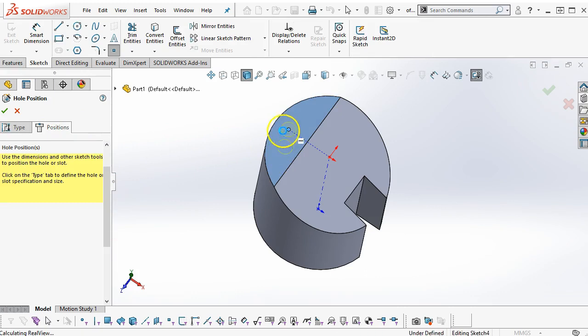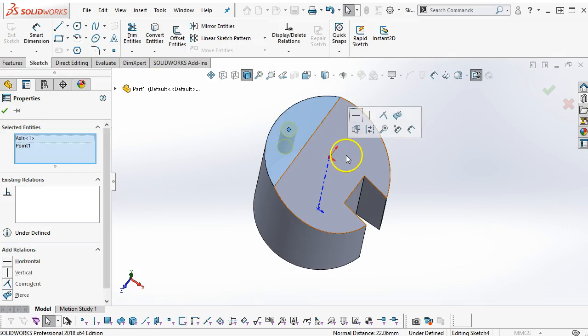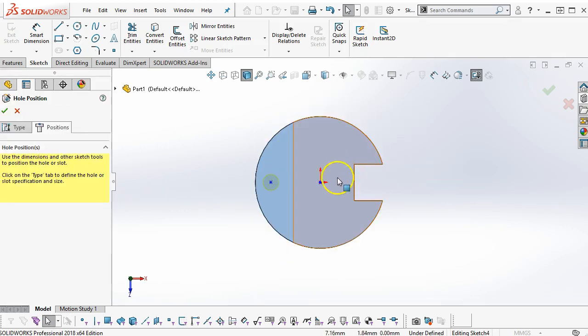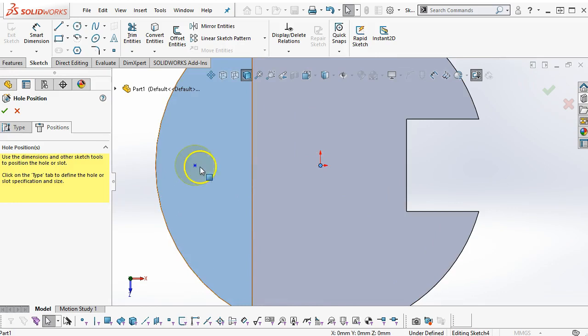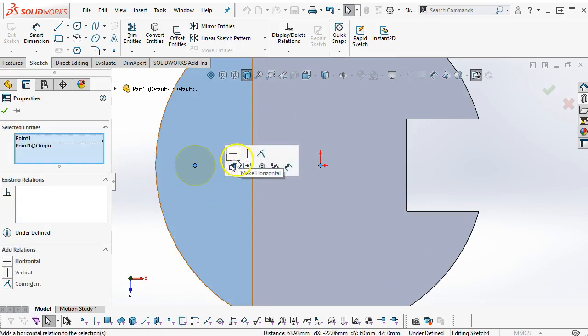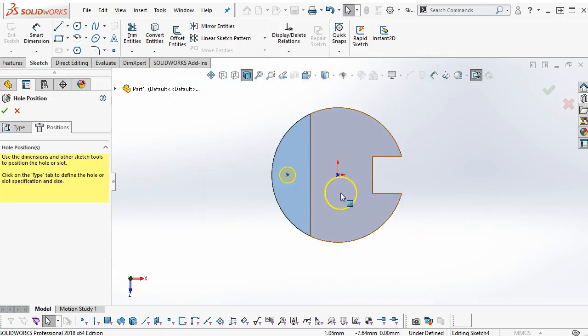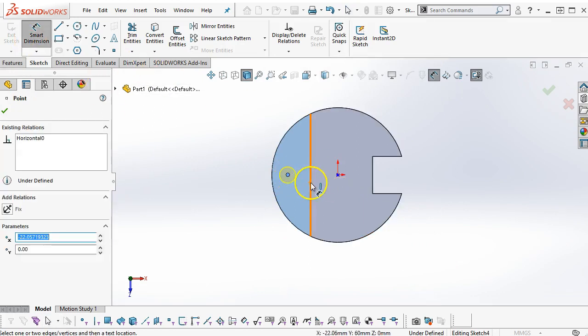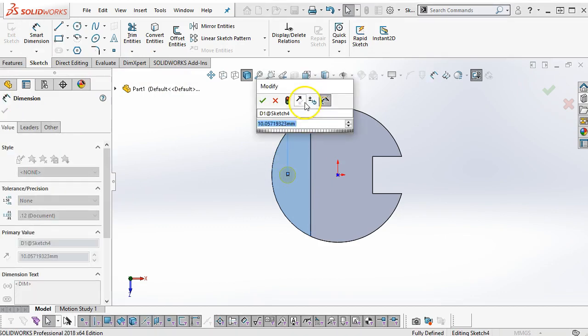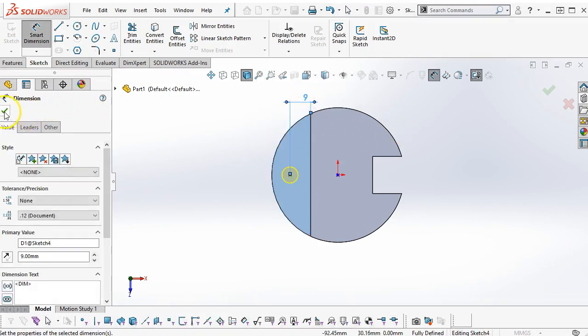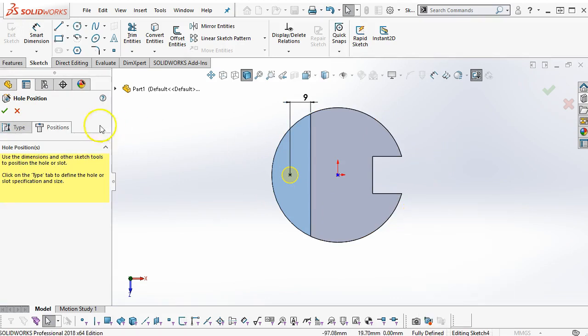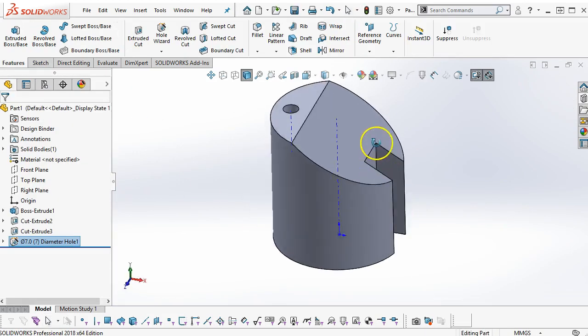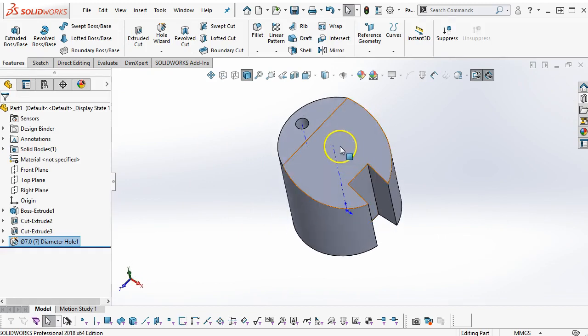We go into the position, set the position. That can be horizontal. Let's go normal 2, Control 8. And temporary axis is still on, so I've turned that off. So we'll set horizontal, and then that distance was 9 millimeters off of the edge. For a datum reference, that's not really what I would want to pick from. It may be good for the design, but when we get into the drawing and the detail, I would want to go off of the center of the part.